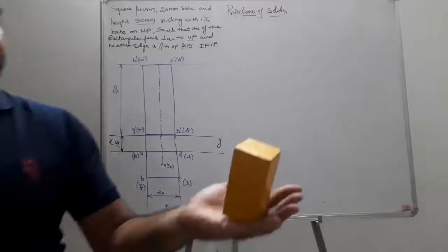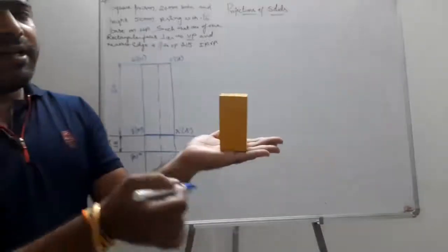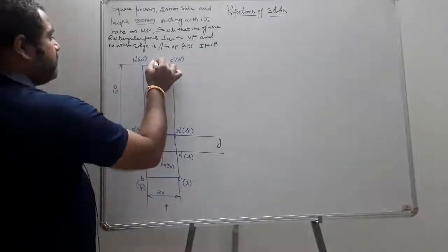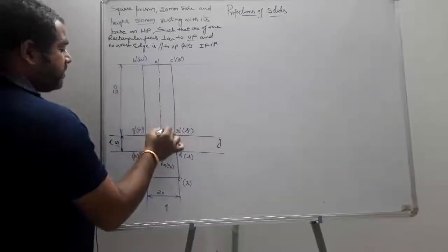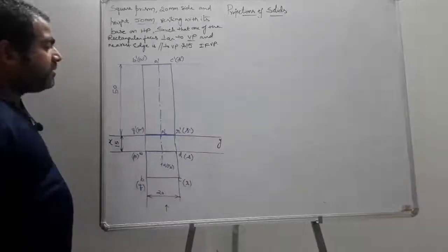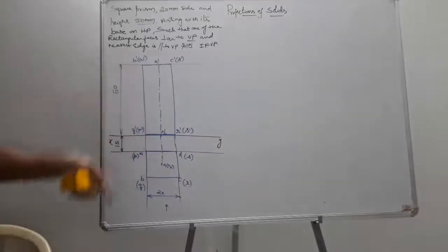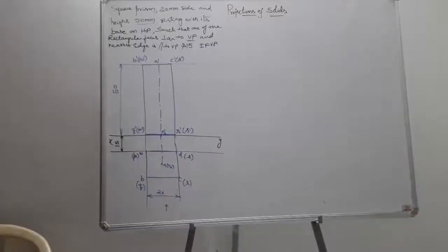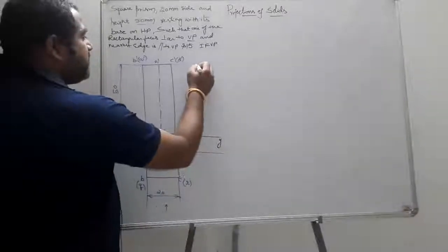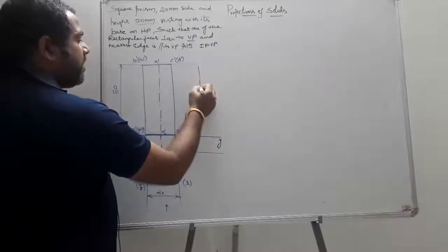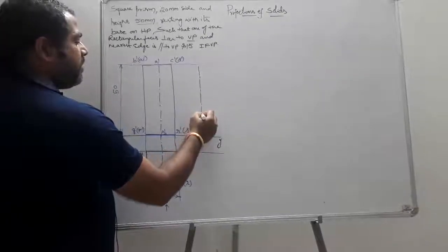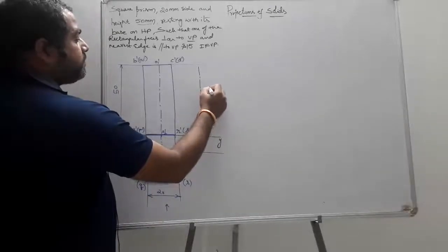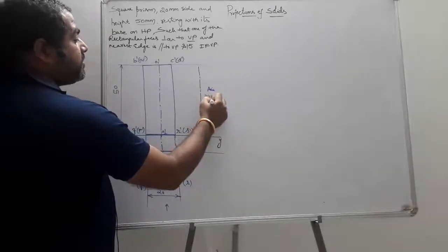Okay. So from the front, you are going to see the height. And also the axis is going to be, here O1 dash, here O2 dash. In front view, the points are with the dash. Always remember, the axis is represented by line, a dot, line, a dot, line, a dot. So this is the axis representation.